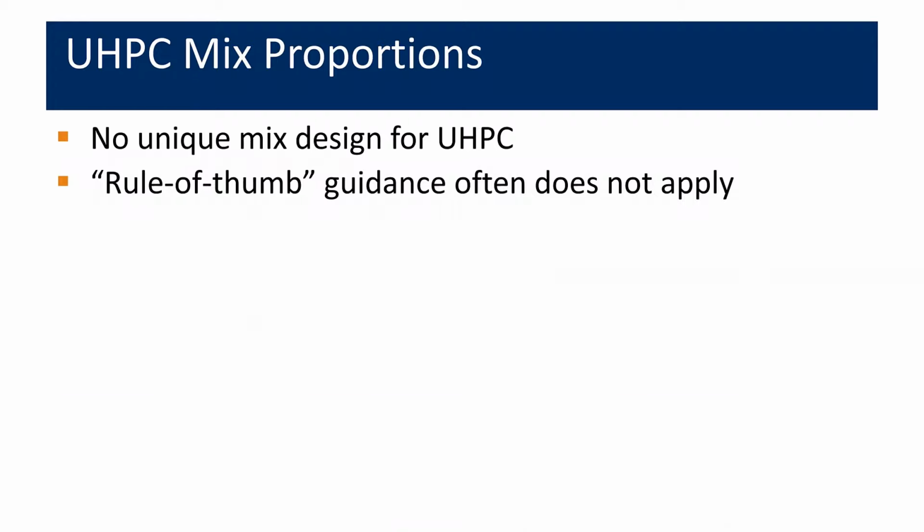When it comes to proportioning UHPC, there's no unique mix design. I can't just pull a mix off the shelf and say this is going to be a UHPC. It might not even work. And the rule of thumb guidance doesn't apply.